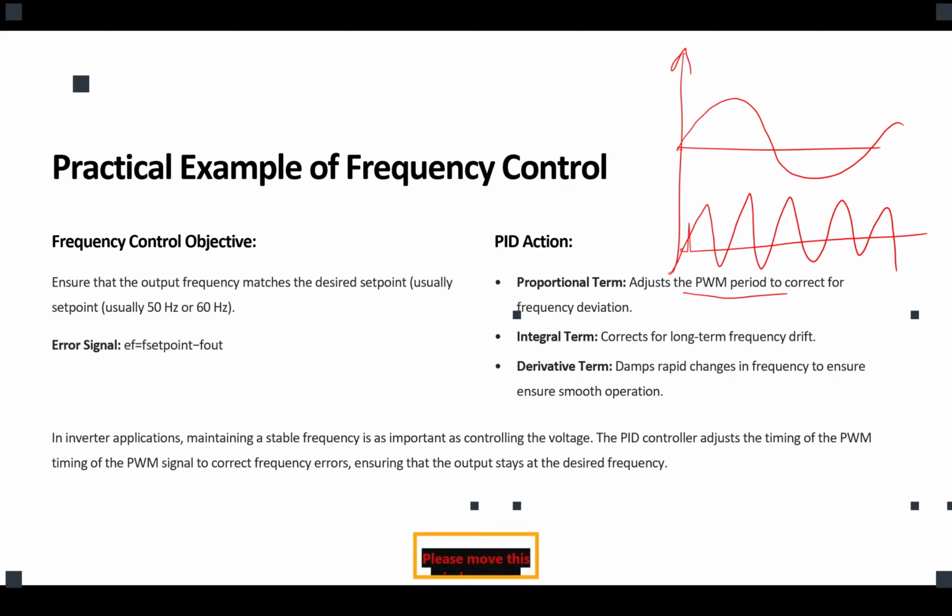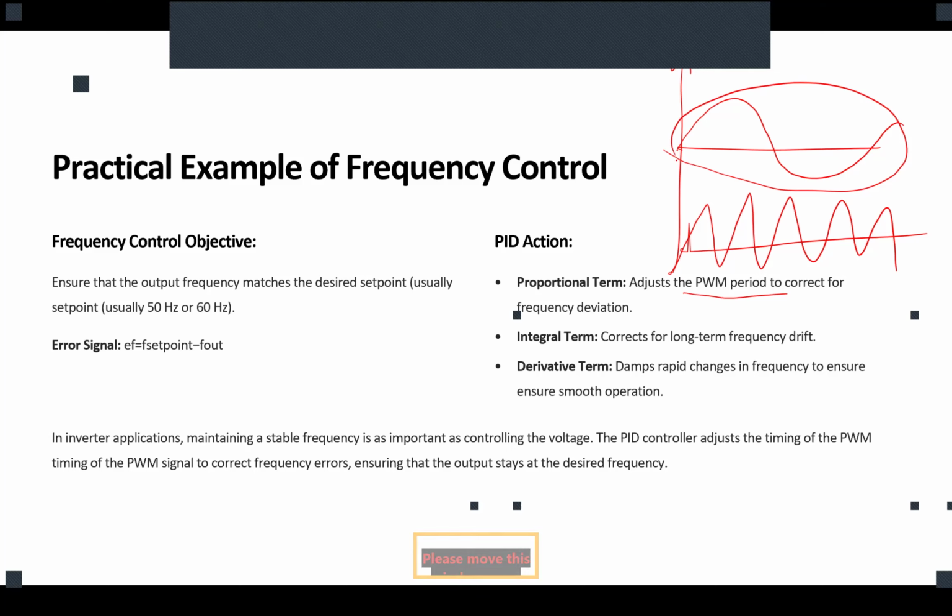The reference signal. Yeah. So the frequency of the reference signal defines the frequency of the output. So if you want to control the frequency, tune the frequency, eliminate the error, whatever you want to call it, you change the frequency of oscillation in your reference signal.